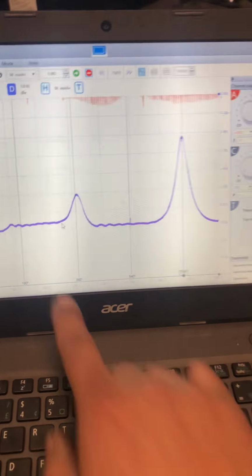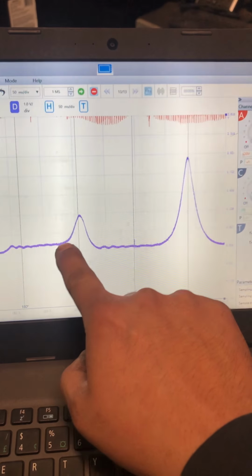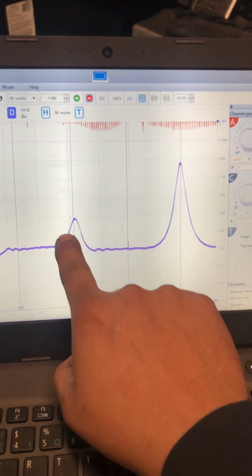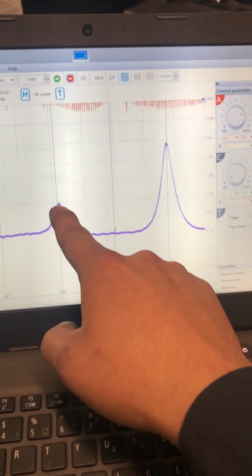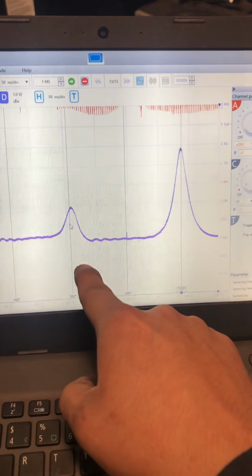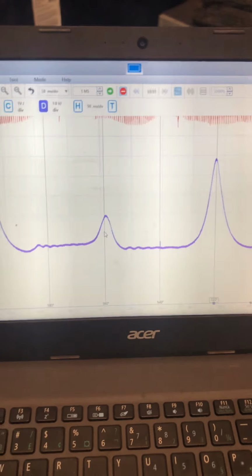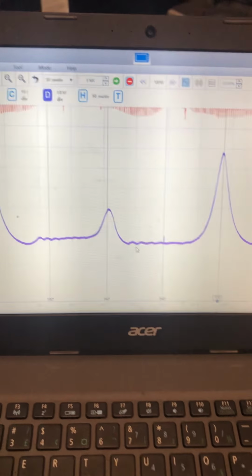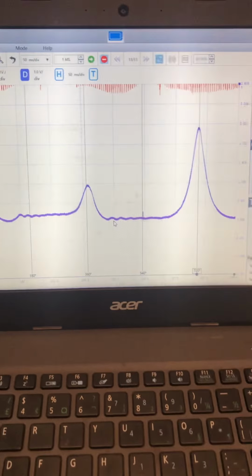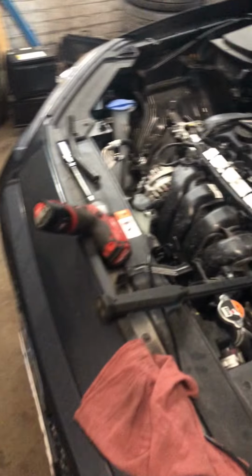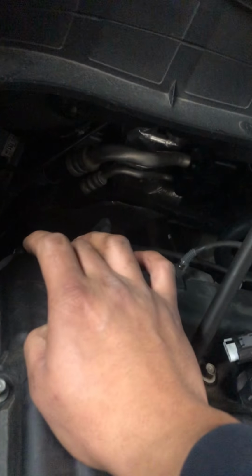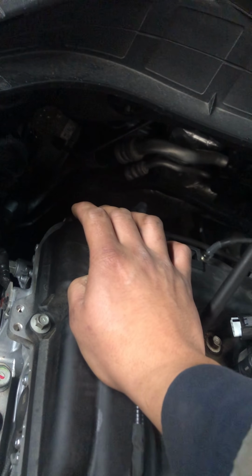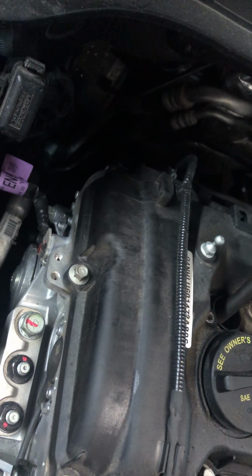As you can see, there's a pressure build-up, right? So I'm thinking that's not opening, because it should open here on intake. So there's something going on in this timing system. Now we just have to verify if it's our CVVT that is the problem, or if it's the chain that jumped.